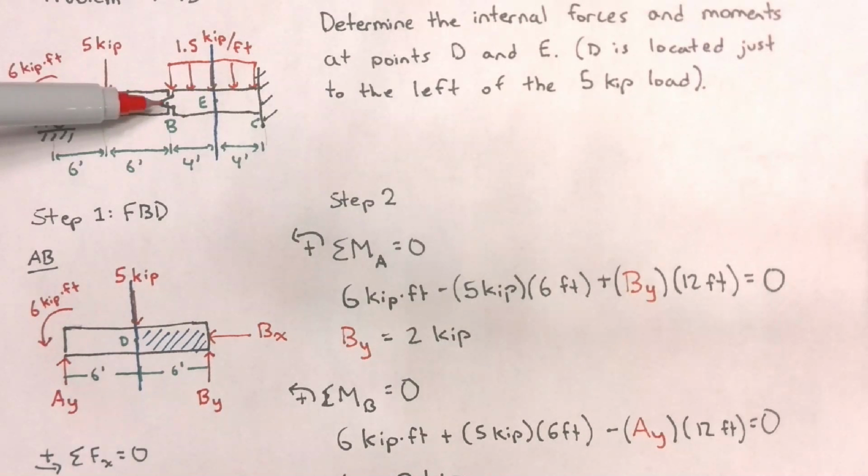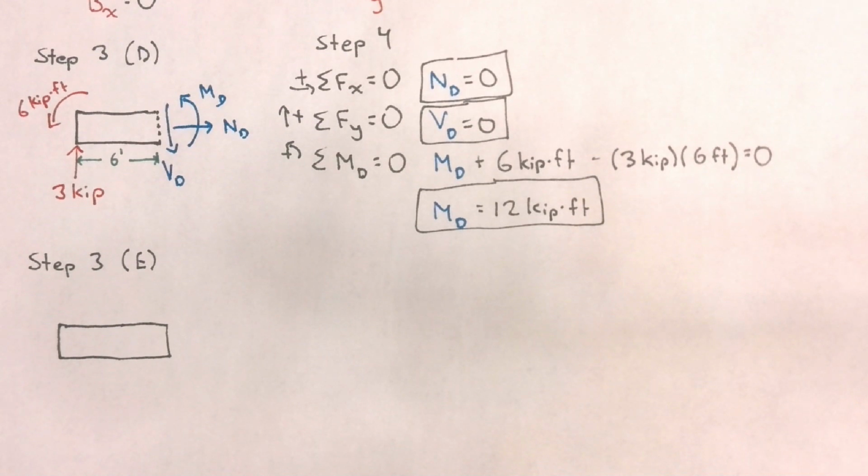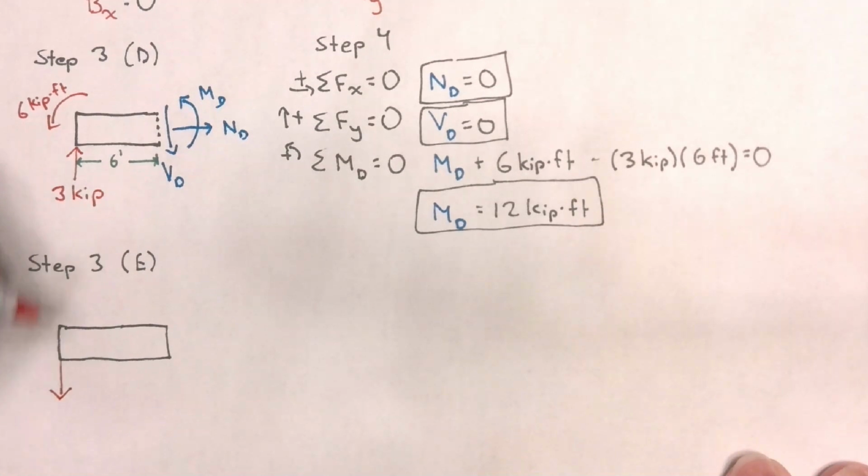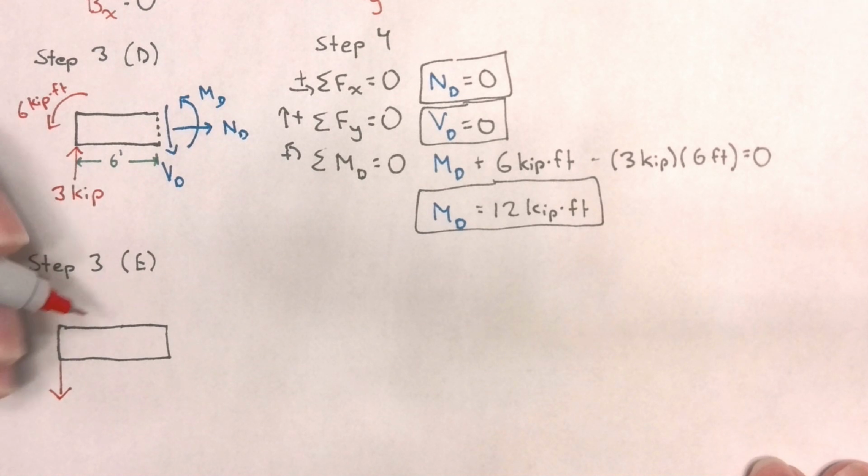This is because both hinge forces from both members have to cancel out in order for the system to be in equilibrium. Therefore, when I draw my free body diagram for member BC from B to E, my reaction force at the hinge will have the opposite direction, so it will be pointing downwards.